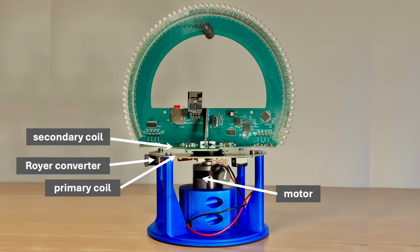It serves two purposes: powering the motor and wirelessly transmitting energy to the rotating LED board. For this, a so-called Royer converter is used. It generates an alternating electromagnetic field. The lower circuit board contains a transmitter coil, while the upper one has a receiver coil. This setup allows a fairly efficient transfer of electrical power to the display without using slip rings.